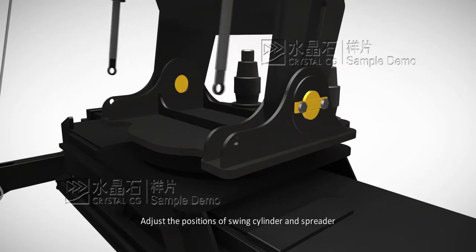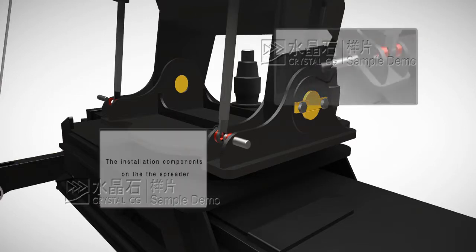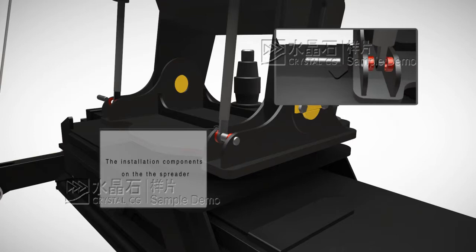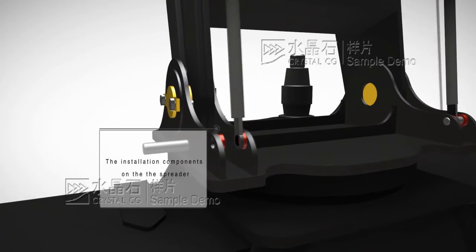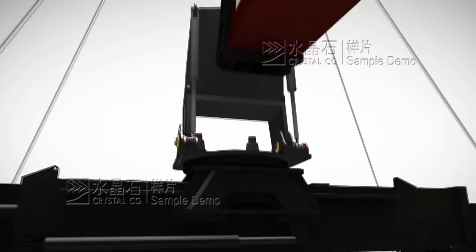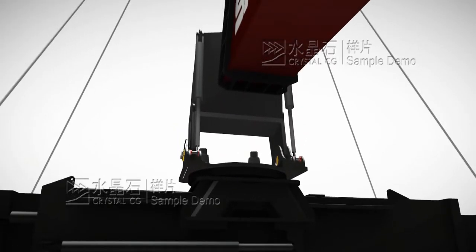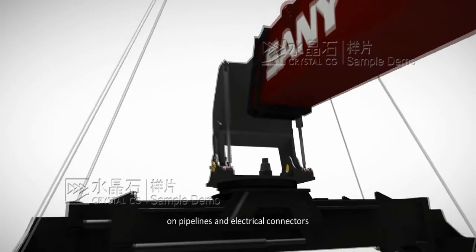Adjust the position of swinging cylinder and spreader. And then assemble the pin shaft. Connect the oil circuit and the electric circuit according to the corresponding marked numbers on pipelines and electrical connectors.